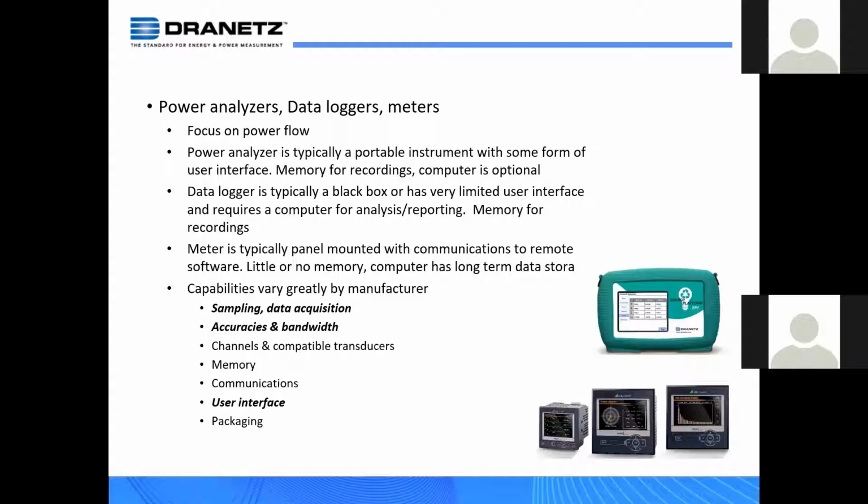And a key thing is if you're interested in check metering, checking a billing meter or anything related to revenue, you want to make sure you have the accuracy of these meters. So maybe the lower end meters won't work right for you. And you also have the transducer considerations that we'll speak about in a couple slides. So just keep that in your thought process. And again, differences are packaging, user interface, the amount of memory. Those are very application specific. So take a close look, make sure your tool is going to meet your needs.